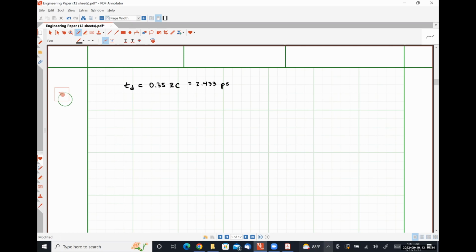Now, let's calculate our intrinsic propagation delay. When we did this for an N-well resistor, our intrinsic propagation delay was much, much shorter than the actual delay time of the RC network, right?